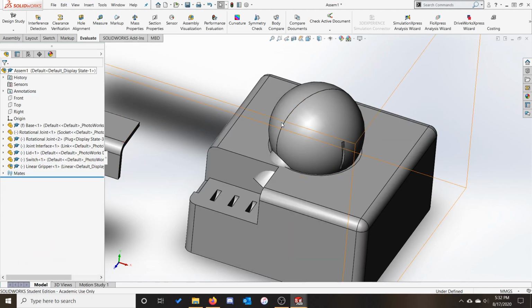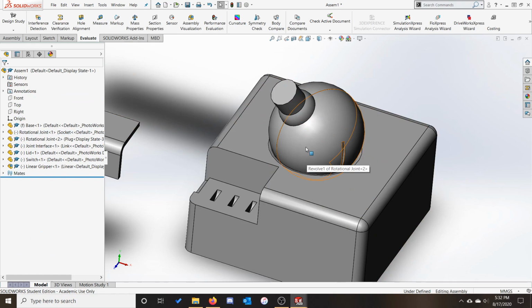This second one seems easiest to fix to me, so we'll start there. We can just exit out of the menu, and then left-click drag to move the component to a place where it's no longer intersecting. The peg one is a little harder to fix, but it is still possible. The problem here is that the peg diameter for this joint is too large for the hole. Depending on the model, you may want to decrease the peg's diameter or increase the hole's diameter. The peg seems more obvious to me, so let's change that one.